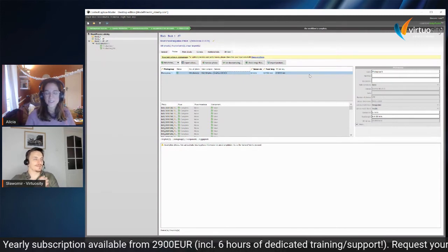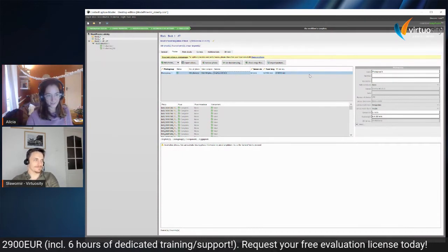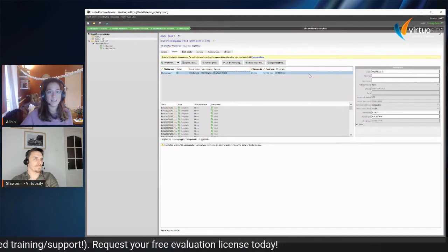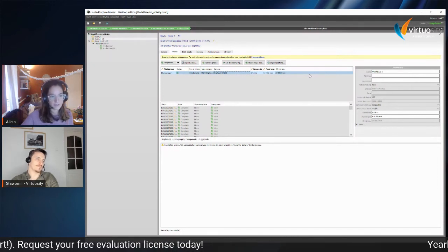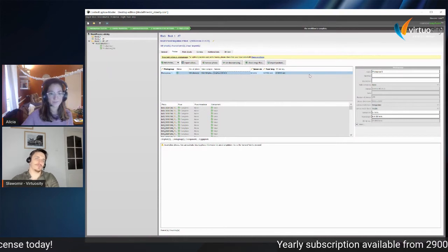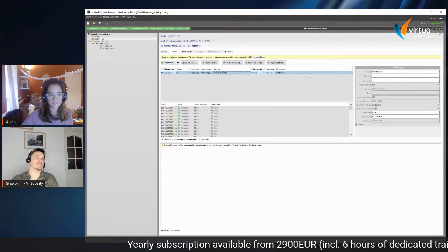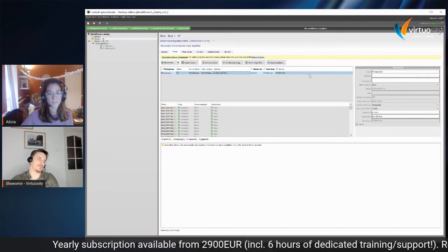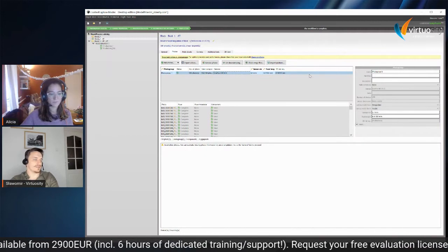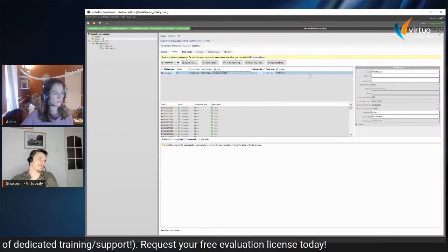Cool. So then you do the AT, you do the scale constraint. That would be your recommended workflow, and then you generate the 3D mesh. Is that it? Yes, exactly. And then, in case of editing, you have a lot of possibilities, including our touch-up tool to clean the noise, then moving forward to the ContextCapture Editor to create vectorization and even prepare some documentation.